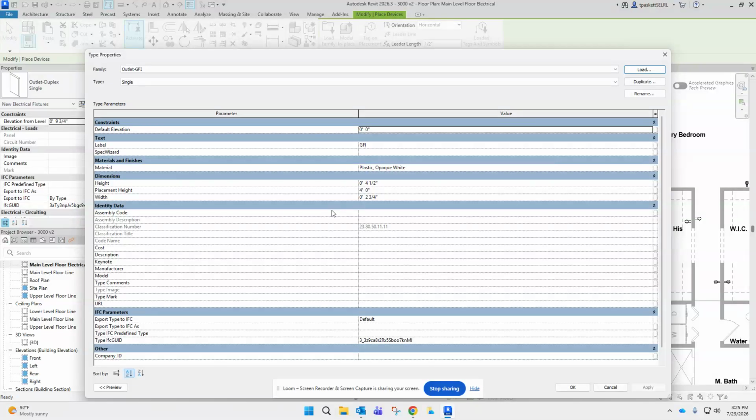So what we've got to do here is you have to make a choice. Your countertops in your kitchen are at 36 inches. You could raise them up to 42, and then this doesn't seem quite so drastic. Or you can lower your outlets here to being 42 inches off the floor. That's 3'6" instead of 4 feet. You can make that determination. I'm going to place mine at 4 feet for right now, and then adjust individuals as needed if it's necessary. Okay, but 4 feet's kind of where I'm going to place them, and here we go.